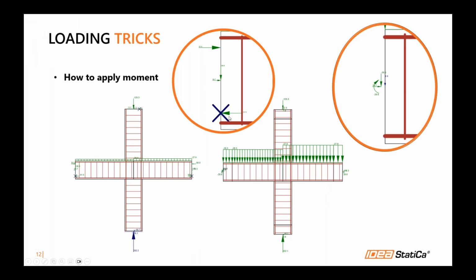I said at the beginning that the concrete is not able to transfer the tension, that everything is transferred by reinforcement, and it's true even for the forces. So when I have a force that's causing tension in the concrete, it would make my calculation unstable or it would fail. So I need to use a load transfer device that will transfer the load straight to the reinforcement. Okay, so I used a patch load. Otherwise, this part would fall out.